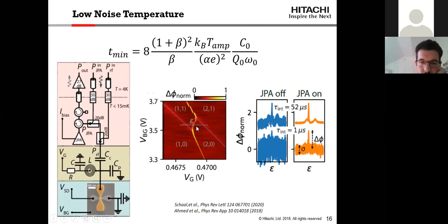Good. So we tune our device using the top gate and the back gate voltage into a region in which we have an interdot charge transition. This occurs by chance in this particular device, and this interdot charge transition is between a dot and a dopant that is in the channel of the device. So this is the transition that we want to measure when doing spin readout, because we will do a projection between the 1-1 state into the 2-0 state of the spin states of the system.